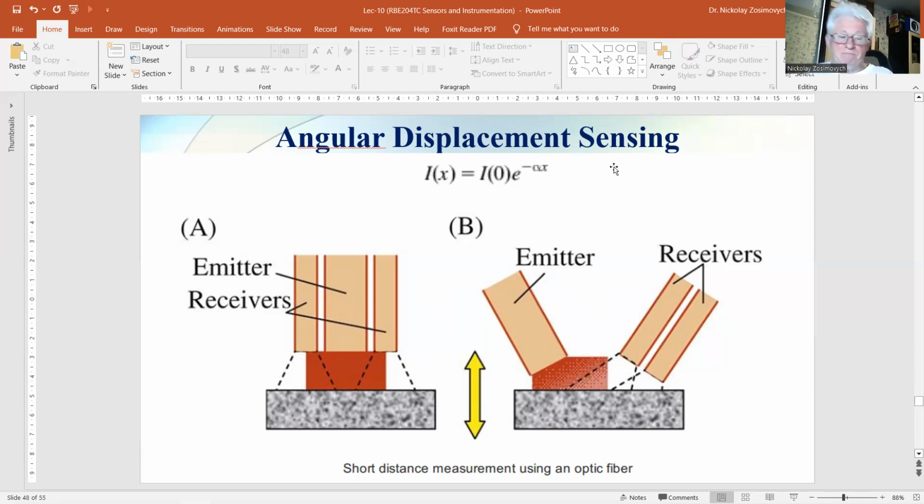This can be a simple optical displacement sensor, in reflected or transmission mode, by an encoder or a vane connected to the other end of the pendulum. Application of a feedback loop reduces error due to, for instance, a strong nonlinear relationship between angle and measured displacement.